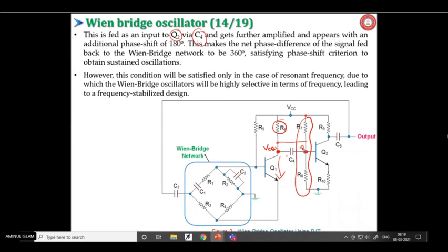So if you connect this coupling capacitor C4, then the DC value at the collector of Q1 is not going to affect the base bias or base-emitter bias of Q2. Is it understood? Yes, sir. We have discussed it earlier also, but you have forgotten. We have discussed a little bit. Anyway, let us go ahead.